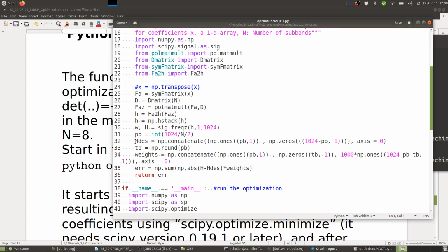Yeah, so here I'm constructing then the desired frequency response as a sequence of ones in the passband. Then we have a sequence of zeros in the stop band. So here we can see the rest is all stop bands. Here I'm defining the transition band, which I'm defining basically as the same as the passband.